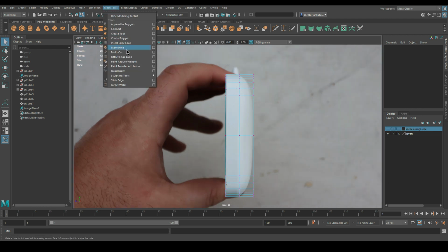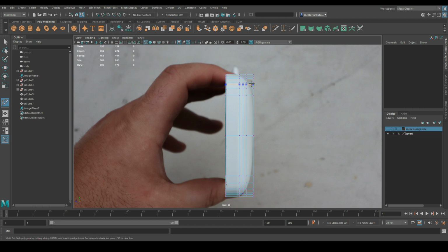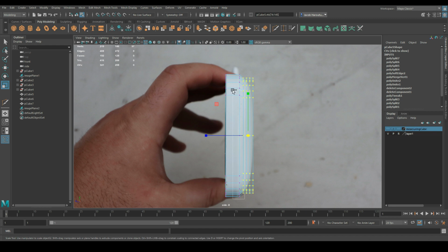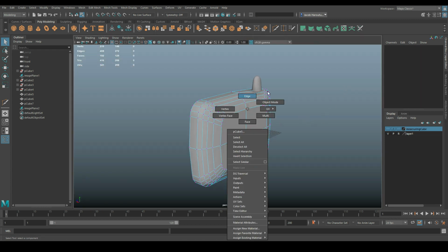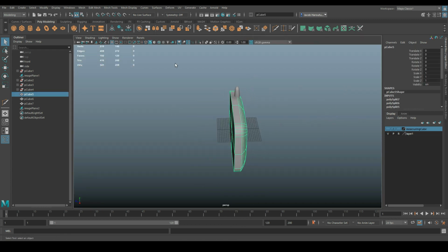And to get that in, I'm just gonna model that in by hand. So I'm gonna add 3 subdivisions there. I'm gonna scale down. Continue scaling down. Deselect these vertices as well. Continue scaling down. And a little bit more. And we got the makings of a screen.